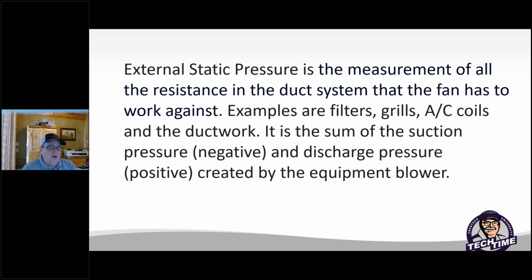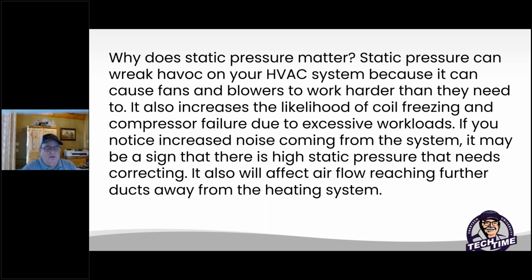So why does static pressure matter? Well, static pressure can wreak havoc on any HVAC system as well as our geothermal systems because it causes fans and blowers to work harder than they need to. It also increases the likelihood of coil freezing and compressor failure due to excessive workloads. If you notice increased noise coming from the system, that may be a good sign that there's high static pressure, and that could need to be corrected. Also, this will affect your airflow reaching the farther duct registers away from your heating system.